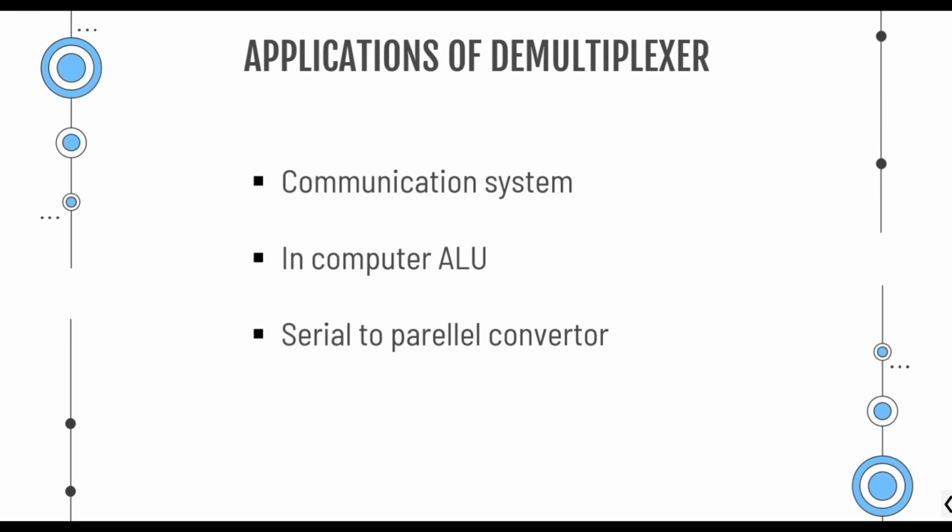A counter is attached to the control input of the demultiplexer. This counter directs the data signal to the output of the demultiplexer where these data signals are stored. When all the data signals have been stored, the output of the demultiplexer can be retrieved and read out in parallel.